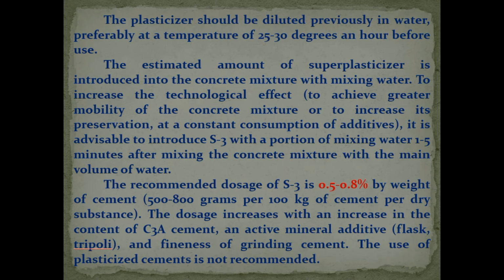The plasticizer should be diluted previously in water, preferably at a temperature of 25–30 degrees, an hour before use. The estimated amount of superplasticizer is introduced into the concrete mixture with mixing water. To increase the technological effect, to achieve greater mobility of the concrete mixture, or to increase its preservation and a constant consumption of additives.